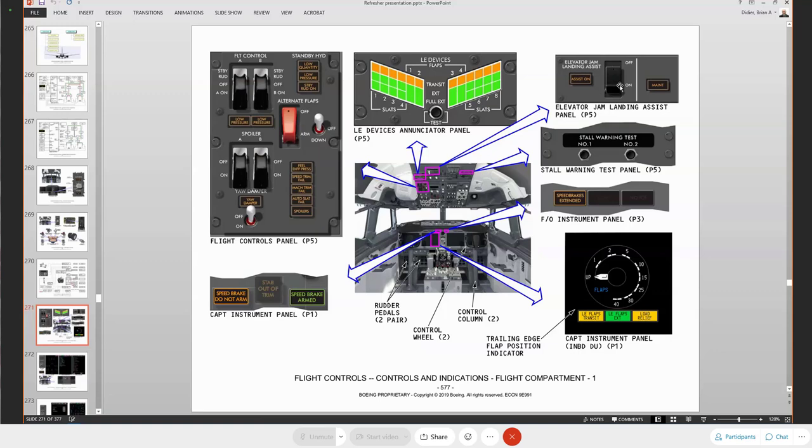The flight spoilers will rise up and extend to about half position, and then the pilots are able to use, by either pushing forward or pulling aft on the column, will cause the panels to either extend or retract, allowing us to control the flight level of the plane. They're going to use that if my aft quadrant of the elevator has jammed for some reason. Okay?